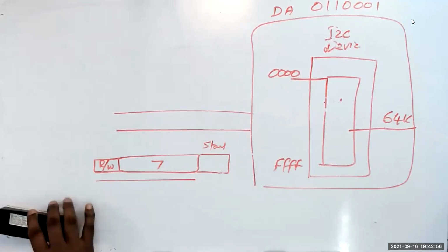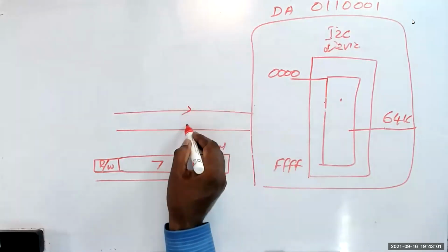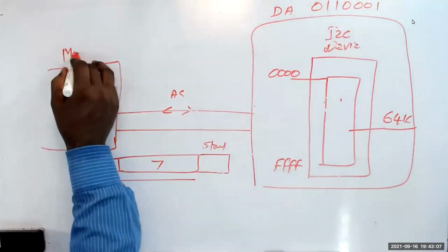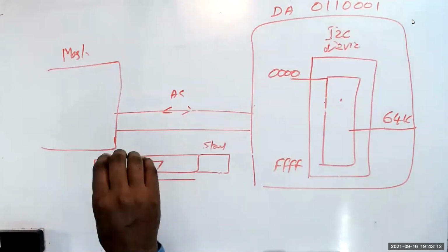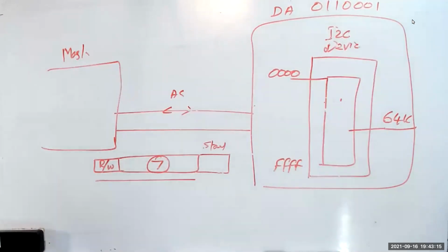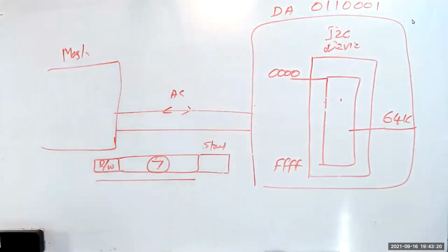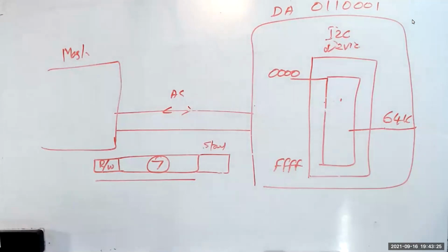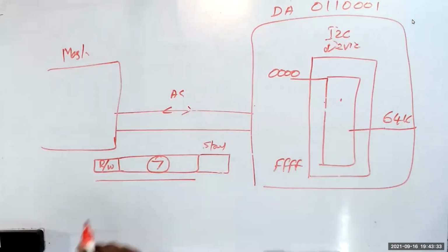Am I right? I may connect so many devices. Now, this device gives the acknowledgement to the master. Finish. Now I selected the device. Now only the device is selected. This 7-bit is not for memory. Please understand, the memory is different, the device is separate. Why 64K? I may be having 1 meg also. It doesn't matter. Now, let us take a small case. I have 64K.